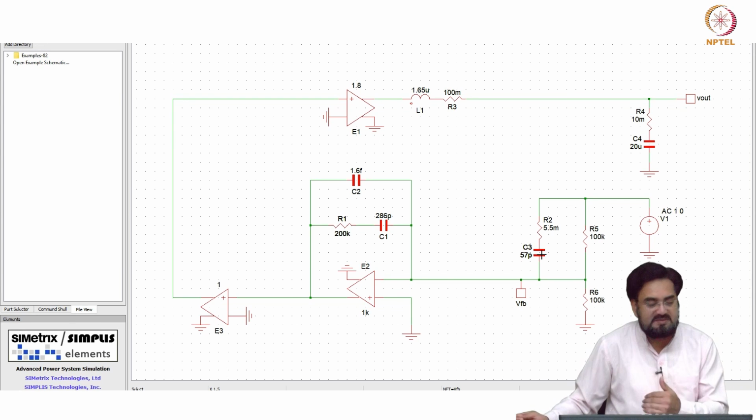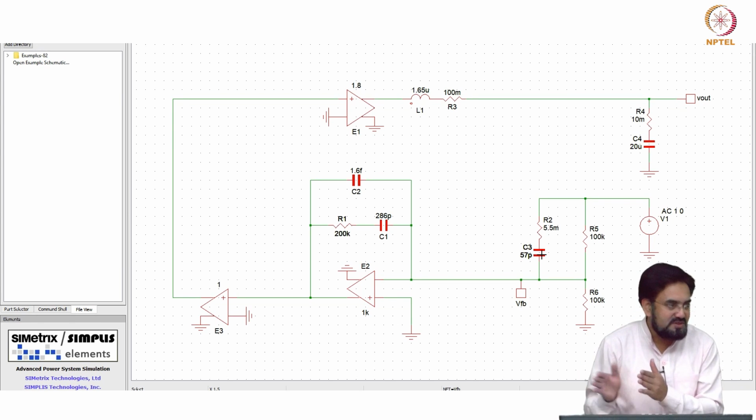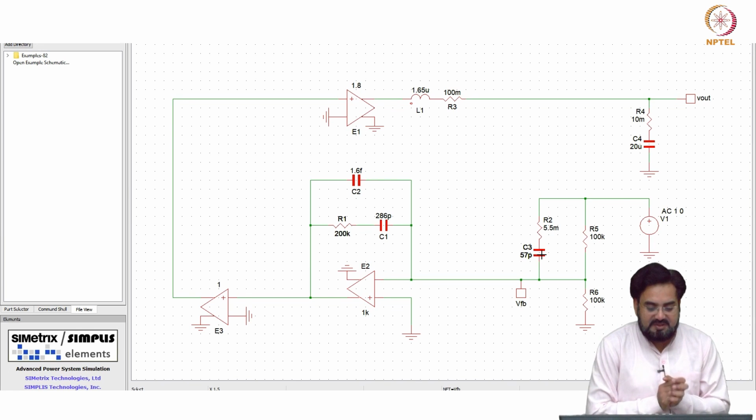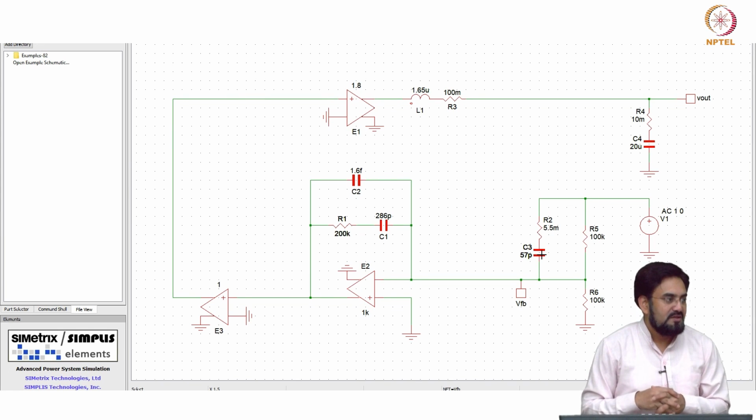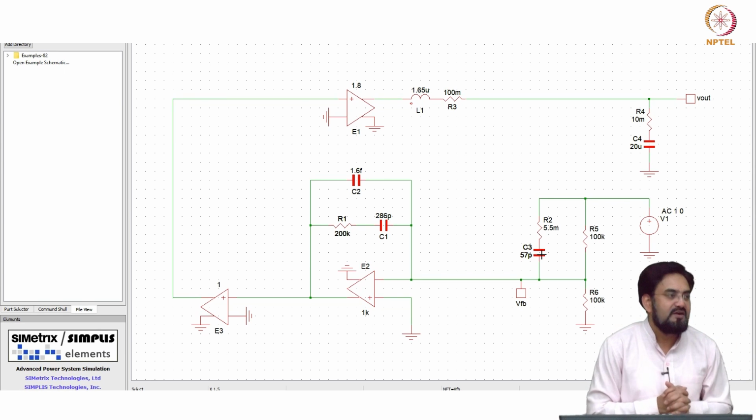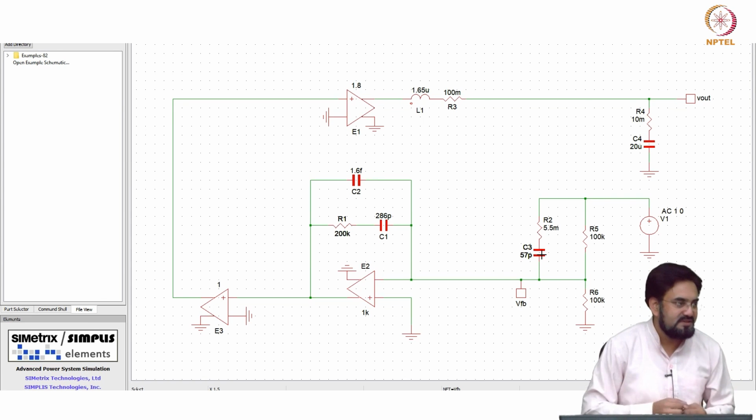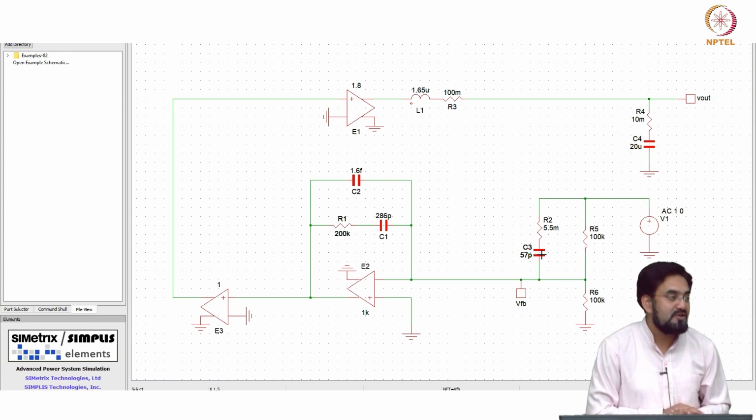So you can improve phase margin by moving these two zeros to lower frequency, but usually we do not want to do that for the first 0. The first 0 we have put at omega naught by 2. The second 0 you can put at omega naught by 2, but moving that lower may not help much. Okay, I mean you may get maybe 2 or 3 degrees, but there is a drawback with that.